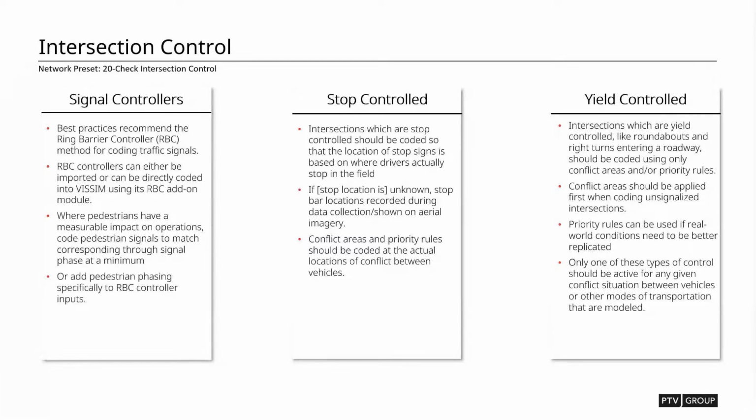And so if that's not modeled accurately in Vissim, then you could be artificially metering traffic upstream, which could affect downstream intersection analysis. So you want to play that game of how accurate do we want to be to the real world versus what should be happening per the rules of the road, quote unquote.